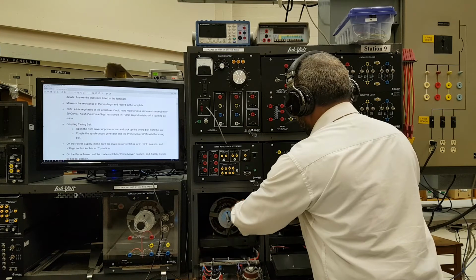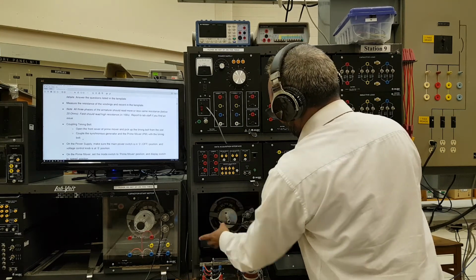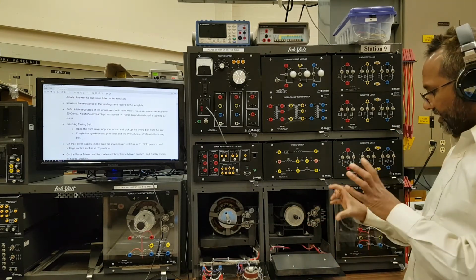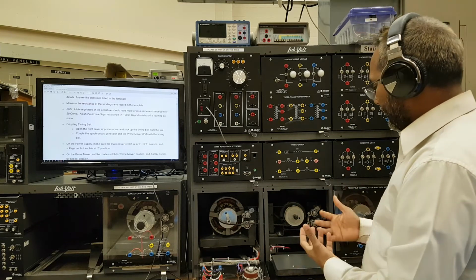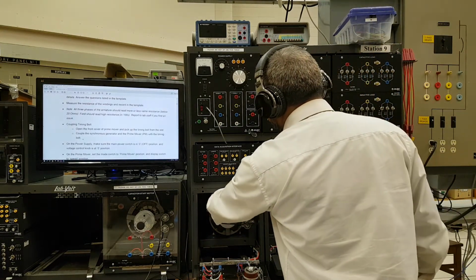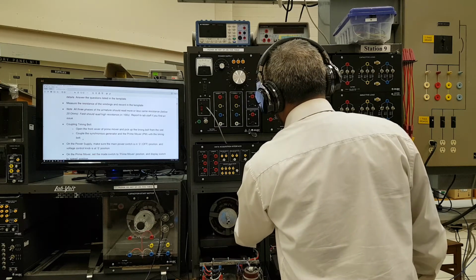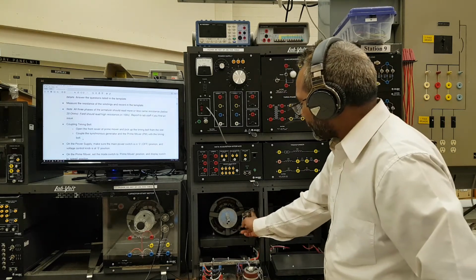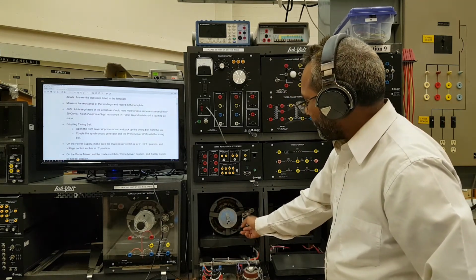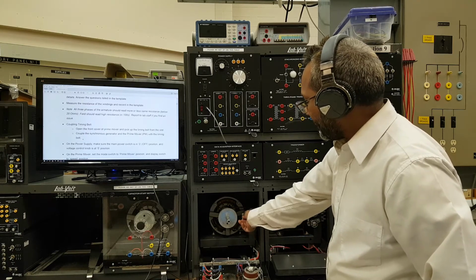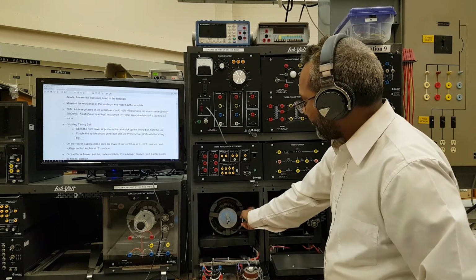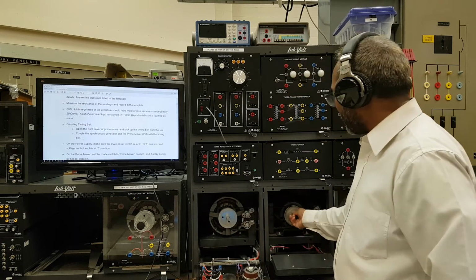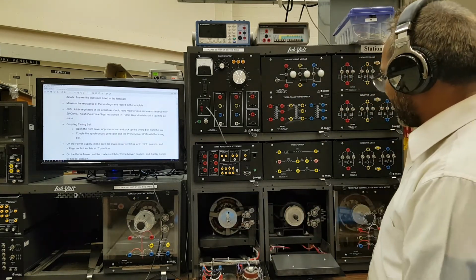When you are trying to work, you need to check a lot of things, whether they are aligned properly or whether there are some issues. When we see things, we can easily spot and rectify them immediately. So when I'm doing this, I also check the ability of this to rotate. Sometimes if they get jammed, it will create a lot of heat, which would be a problem. I would also check the free rotation of these parts.